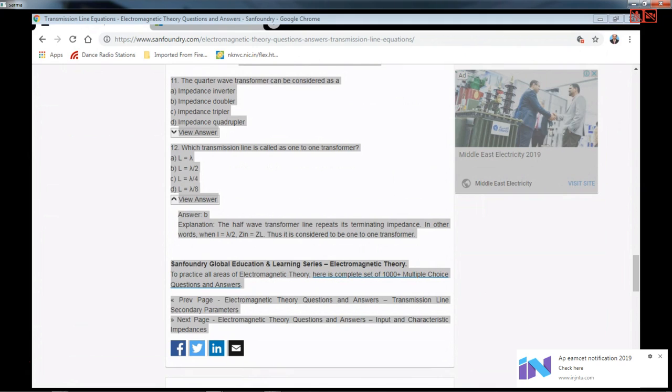Otherwise, most of the unfortunate situations are that people expect the answer for gamma as 0 to 1, which is not correct. The range of values of gamma is -1 to 1 because amplitude and phase are both included, whereas the magnitude only changes between 0 and 1. So please be careful when you are answering this type of questions, particularly in electromagnetic waves and transmission line subjects. People give you some confusing or ambiguous questions in general. So let's be careful about it.